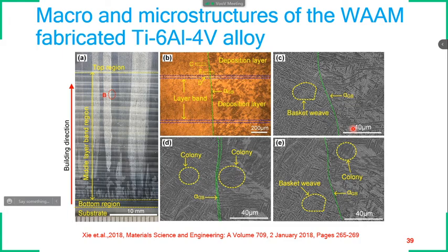Okay, so as far as titanium 6Al-4V is concerned, the most common expected structure is a basket weave structure, which is a typical morphology for this titanium 6Al-4V alloy. So this kind of titanium has a dual phase: one is alpha titanium and the other is beta titanium. Especially in WAAM, the alpha titanium phase will be the major phase and beta titanium will be very minimal. It will be determined only by the solidification rate. Okay, so based on how fast the solidification is, the alpha and beta phases can vary.